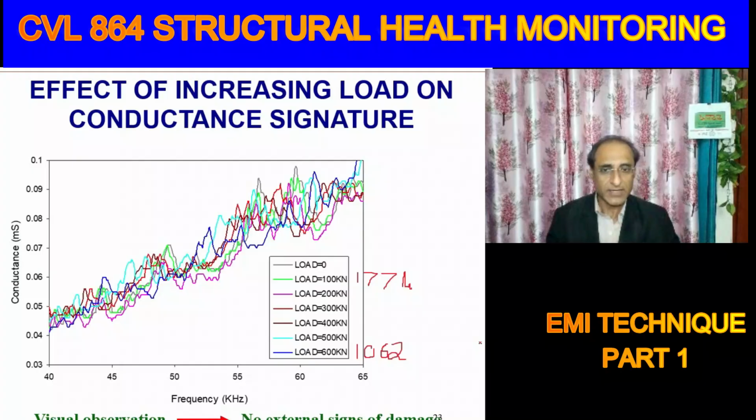But then here the concrete cube is inherently undergoing fatigue, right? Because it's a repeated loading. So it is undergoing fatigue. But till 600 kilonewton externally there was no sign of any damage. Possibly the damage was inside somewhere, and we were seeing some changes here in the signature.